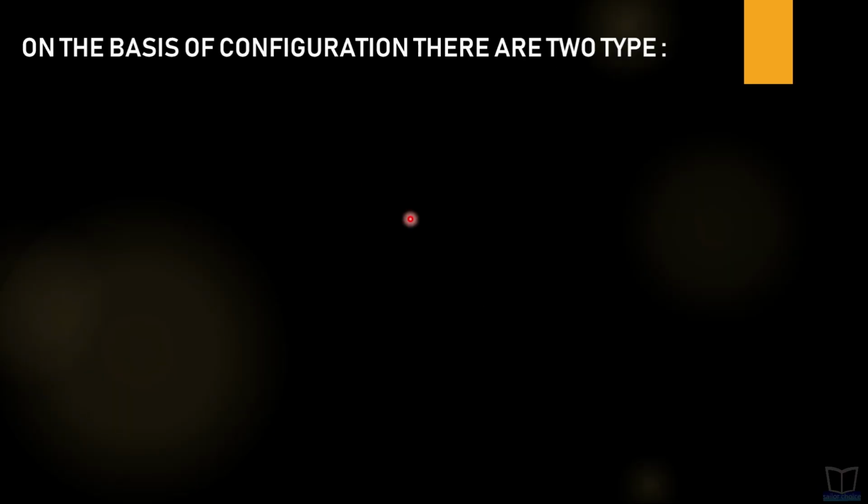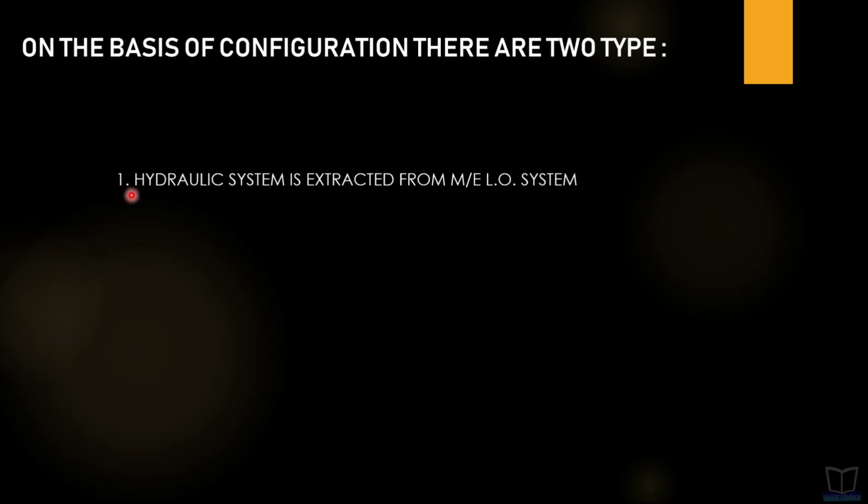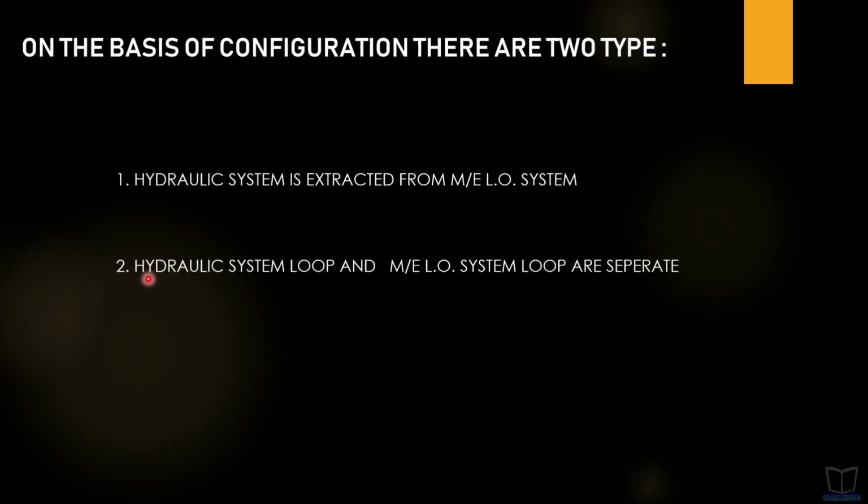Now moving next, on the basis of configuration there are two types. First one is where the hydraulic system is extracted from the main engine lube oil system, and the second configuration is where the hydraulic system lube and main engine lube oil system lube are separate. But in both cases, main engine lube oil is used as hydraulic oil. So please do not get confused that hydraulic oil is something different. Hydraulic oil is the same as the main engine system lube oil.